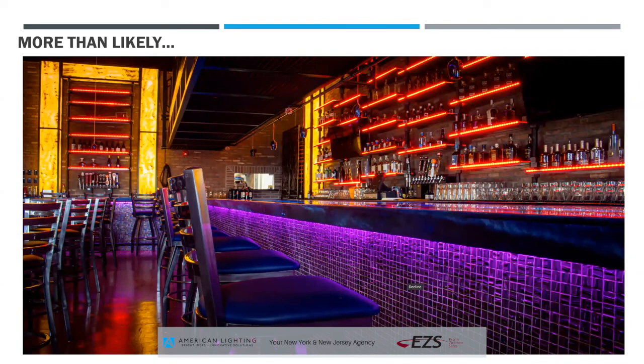Yeah, so that bar that's purple right there, it could be using 3 DMX addresses. Maybe if it's RGBW, it's 4 DMX addresses. If we change that to pixel level control, where I can control every 2 inches of that tape, then I am probably close to, if not more than, a DMX universe on that bar, going the full 90 degrees of that bar. So you can see how things can really add up depending on what you're controlling and the amount of points of light that you're controlling. But if anybody has a 100,000 or a 100 universe project, please come to us.